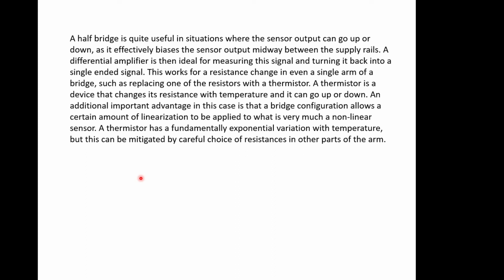Might be a different course, but if you operate an op amp on a 0 to 5 volt supply or a 0 to 3 volt supply, if you want to operate off a battery, then it's tricky because most inputs tend to be referenced to 0, and if that's the case, then you need an amplifier that can measure down to 0 volts, which is your negative supply rail, accurately.